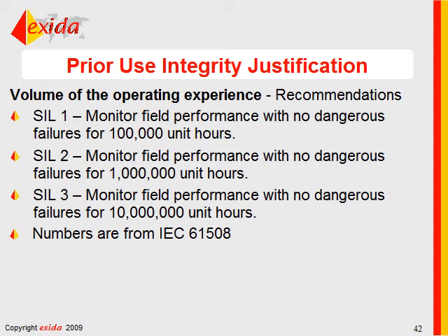All certified products should have a safety manual. The manufacturer certainly produced a safety manual during the certification process, and I would guess they are typically available. Now, warranty return data: most of the time in certified products, an FMEDA report is available, and I will tell you that during FMEDA analysis, warranty return data is reviewed, although I will say most manufacturers don't give you that information directly. You would have to go ask for it.